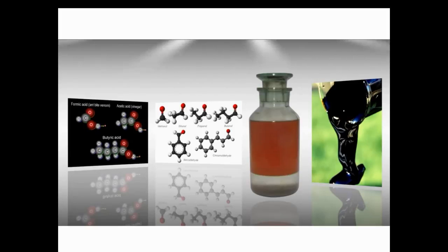But what's inside? The following bad products come from oxidizing oil and then take up residence in the paper insulation. Acids: low-weight molecular acids, fatty acids, free water, moisture, dissolved and in emulsion, visible asphaltene sludges as well as dissolved asphaltenes, peroxide gas, alcohols, metallic soaps, aldehydes, ketones, lacquers, color pigments.